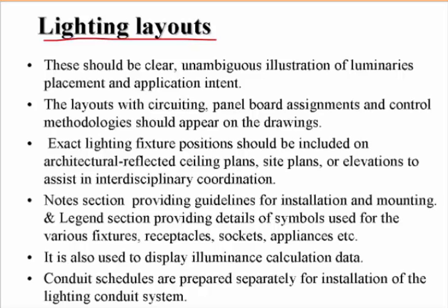Now this should be very clear. Illustration of where the luminaires are placed and the application intent. So the layouts with circuiting, panel board assignments and control methodologies must appear on the drawings.